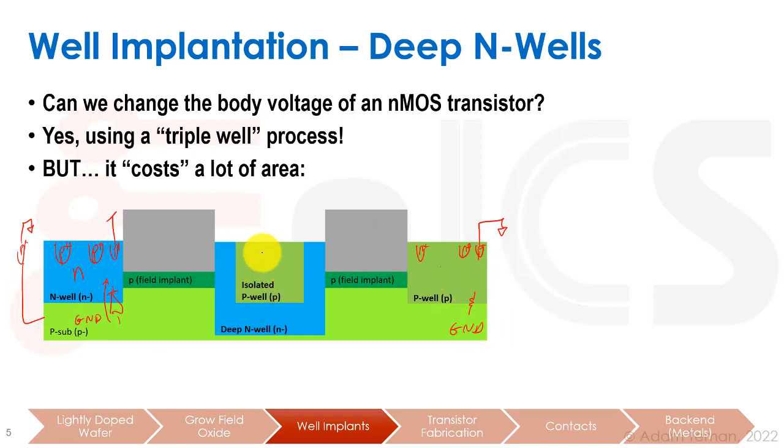But we want to make a transistor over here that's going to be an NMOS with a different body bias. So we're going to put two N pluses over here. We're going to get our nice transistor over here. And we want to actually stick a P plus over here that is connected to some sort of VB, which is not ground. But if we had just done it over here, we're going to cause a short. We don't want that to happen.